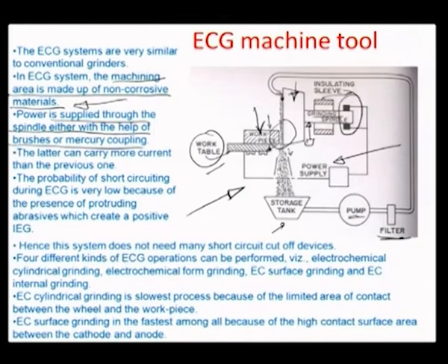So this right here probably is the arrangement for the brush. So there is always a tendency of the brushes to go past the rotating spindle, so that there is continuous supply ensured on the wheel. Okay, from the power supply side, there should not be any break. And if you have mercury in between, which is a metal that has a tendency to coalesce more than adhere, it basically formulates a thick layer between the outer, which is the stator, and the rotor, which is the inner spindle.